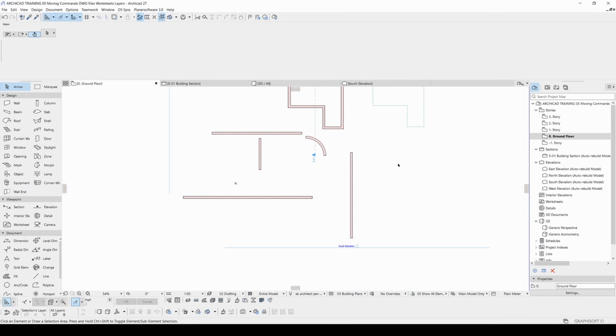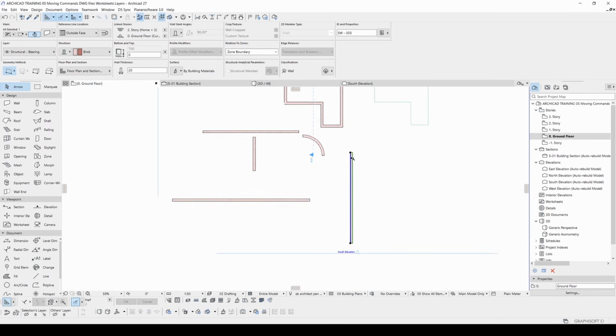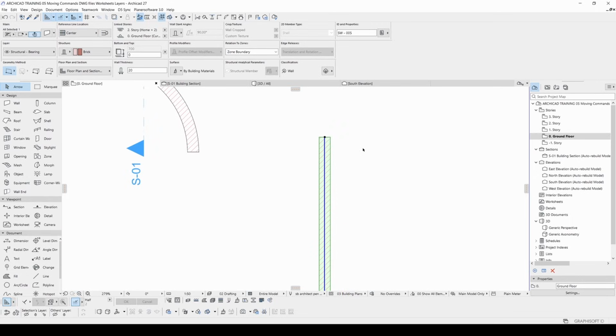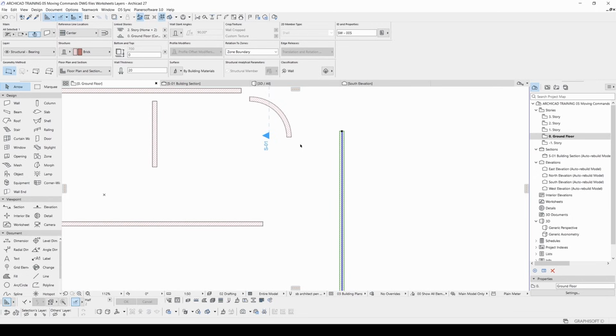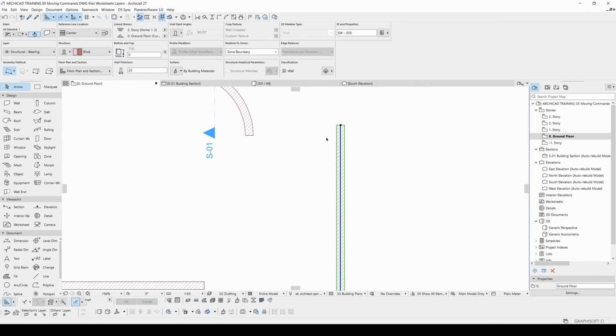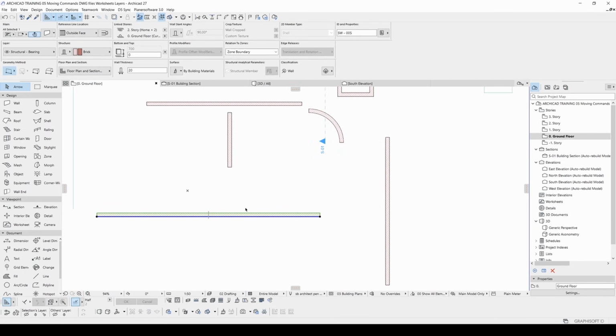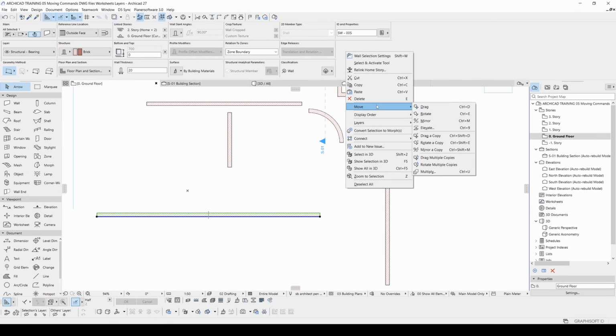my object. For instance, I want to mirror this wall according to this wall center, but I need to determine this wall center. Therefore, I'm going to change the reference line location from here. I'm going to make this center. You will see wall position changed, and if it is mispositioned, you can fix its position with the drag. And after that, I'm going to click my wall, move, and I'm going to click mirror a copy.